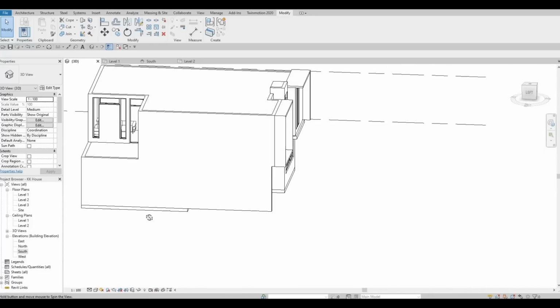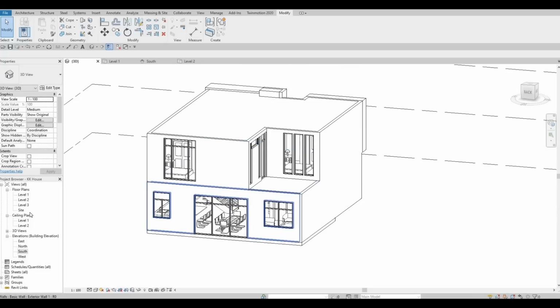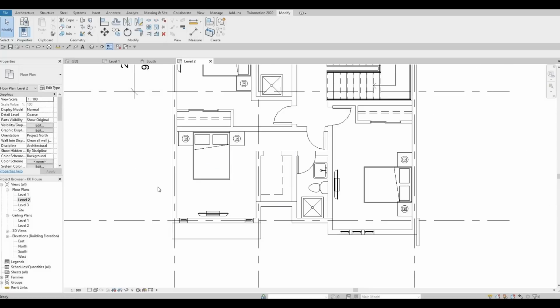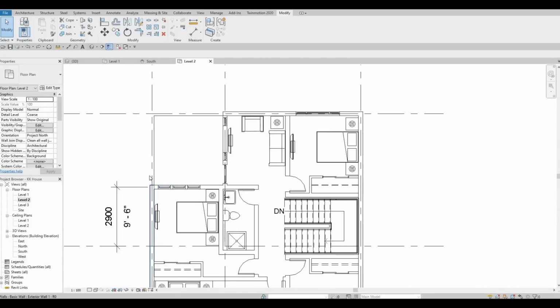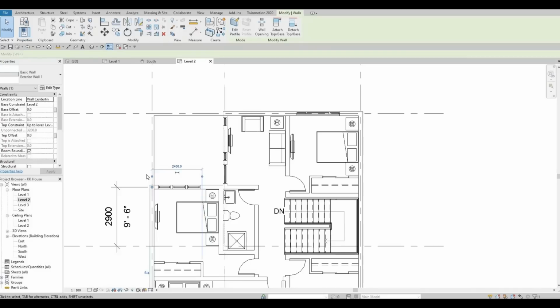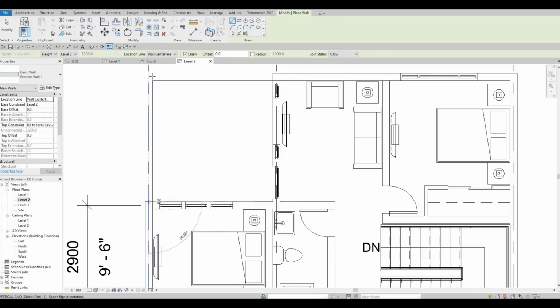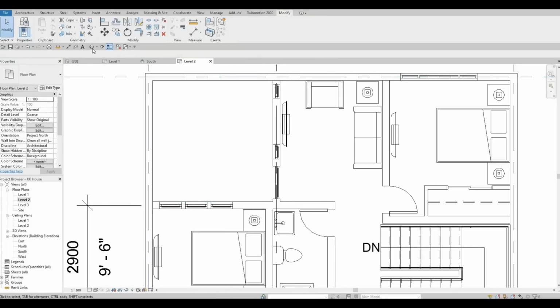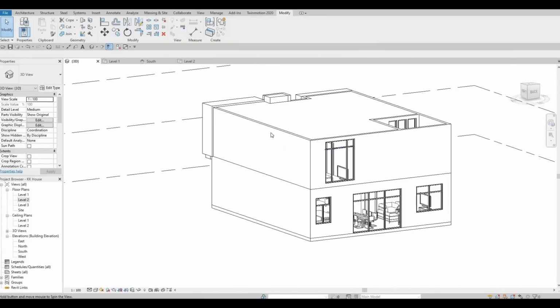And then now, let's go on the back. Let's go to level 2. I'm gonna add in the same wall here. So what I'm gonna do is, I'm gonna type in CS. That's create similar. And I'm just gonna add this one. Then I'm gonna pull this down.